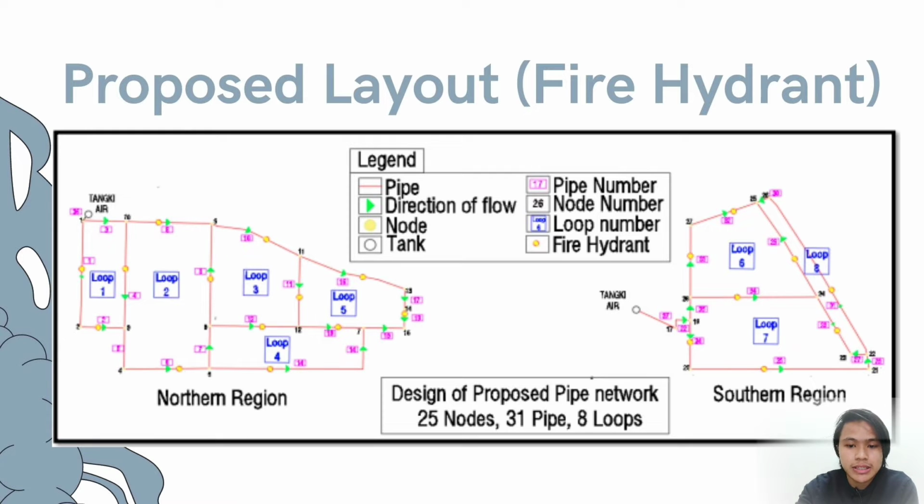A closed-loop pipe network is used to analyze the reticulation pipelines for the project. By using this network, water supply could reach every commercial lot even if a part of the pipeline is closed for maintenance. Besides, enough water is available for the fire hydrants, as the hydrants draw water from the various branch lines due to interconnections. Water is available at every point with minimum loss of head.